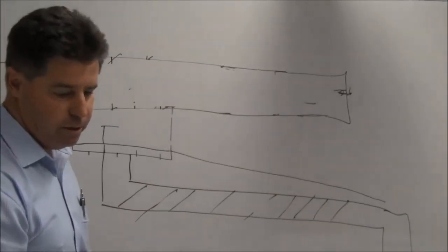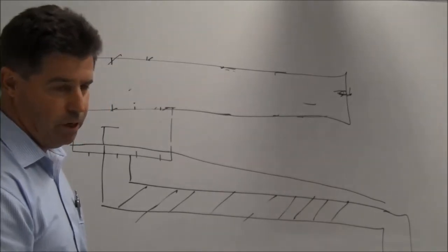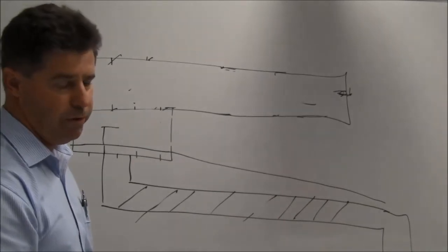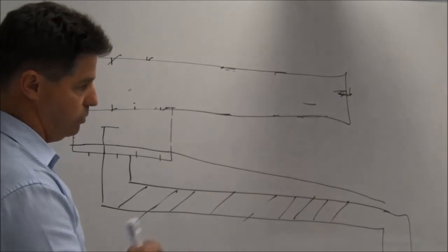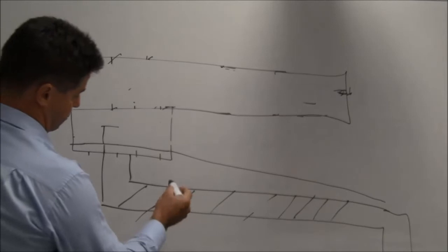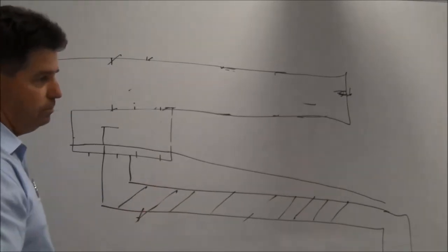But again, they're contained in part 2, aren't they? Yeah, the losses in the pipes. So just be aware of it, that's all. There's nothing wrong with doing it, but just make sure you do calculate the losses. So basically what we do on a plan is we'll say the invert of the pipe has to be a particular depth below the sump.